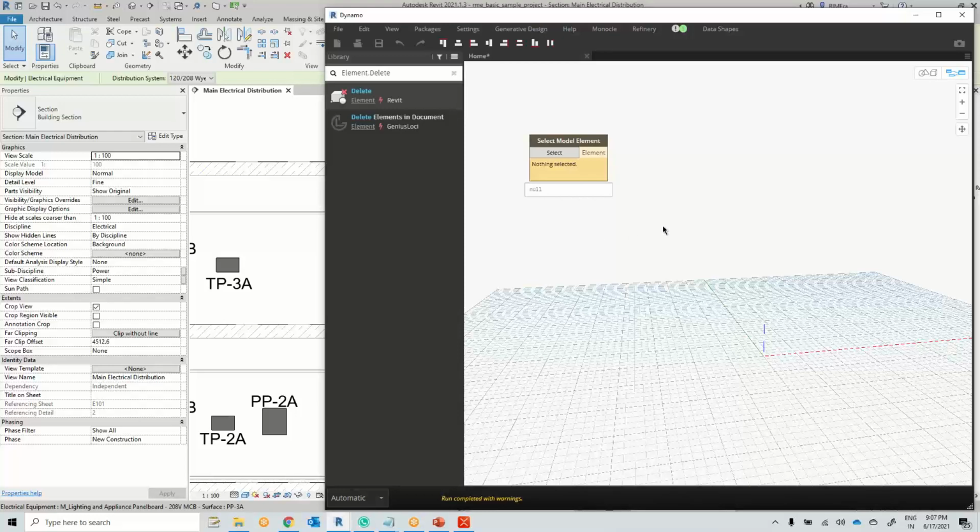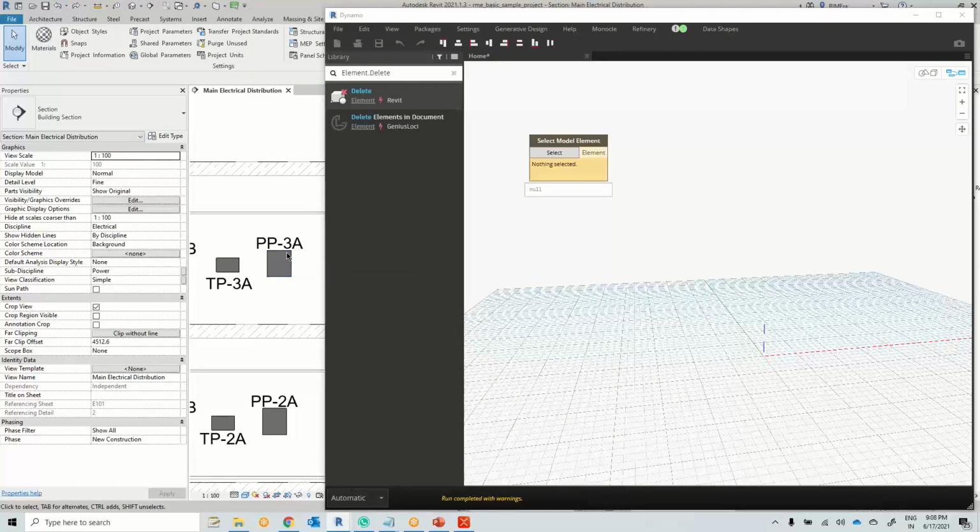I'll explain. There is an undo here, and if you check here, there is a Dynamo script execution. It says I have executed a script 3 times. I have 3 undos here. If you want to see your element back, just undo within Revit, because the action happened in Revit itself. When I go back and redo again here, it will place all the nodes back.